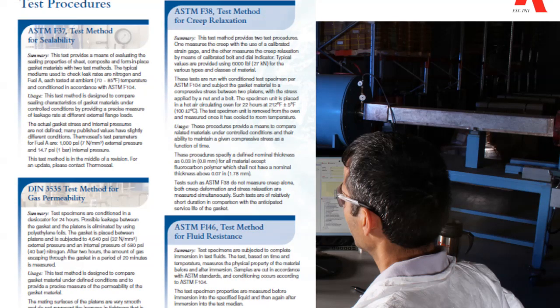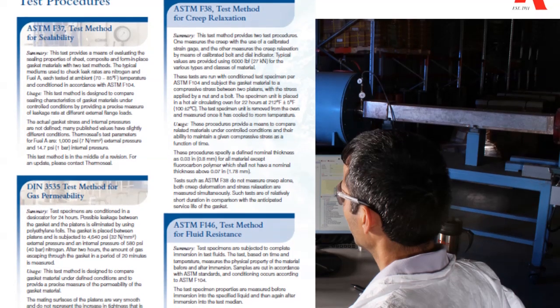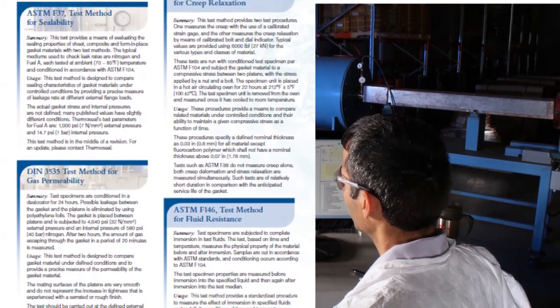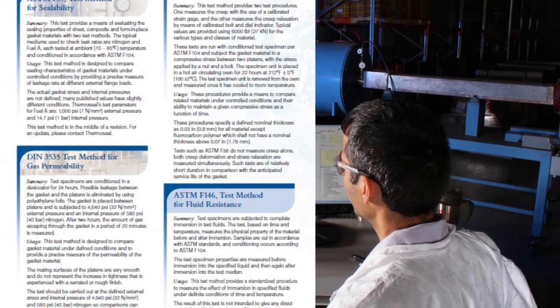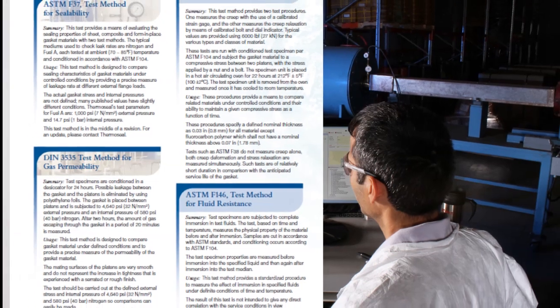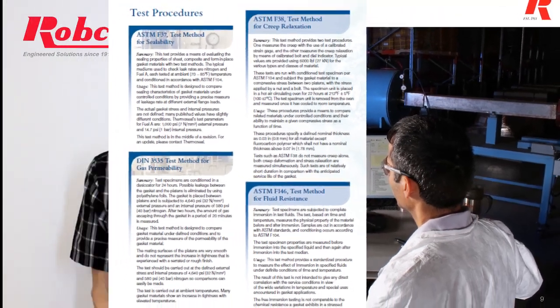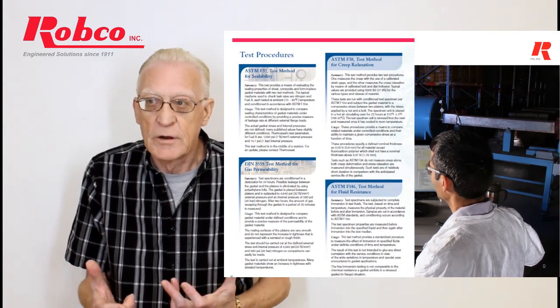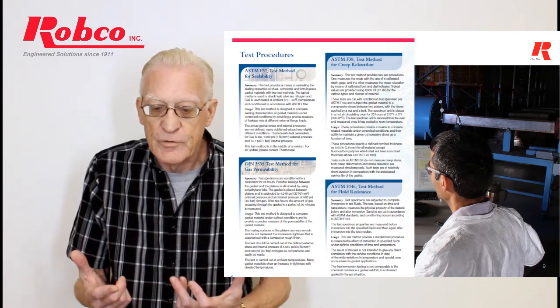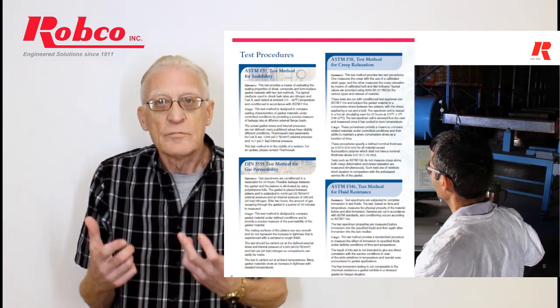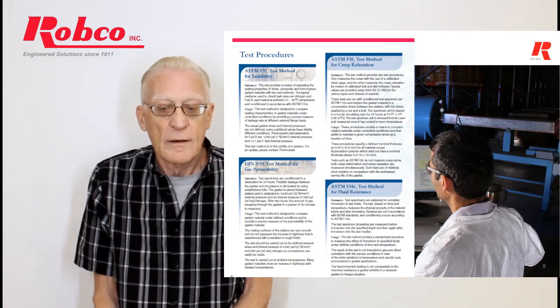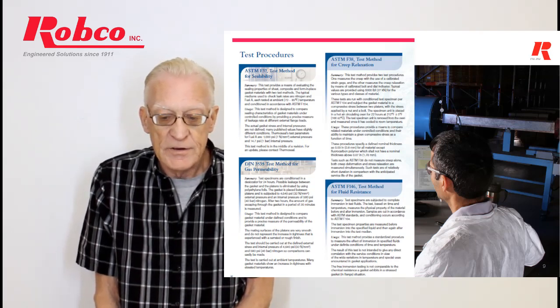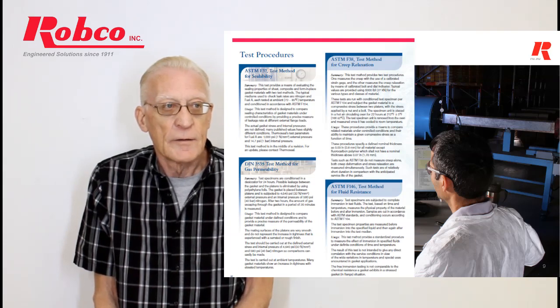So you as a consumer will know what happened to it, and therefore you can compare, okay, if you put 5,000 PSI load on that gasket, it'll compress this much. Everybody is comparable. As I mentioned, the American view of testing and the European view of testing differ in technicality. They're all trying to achieve the same goal. A couple of the different tests ASTM do are compressibility.